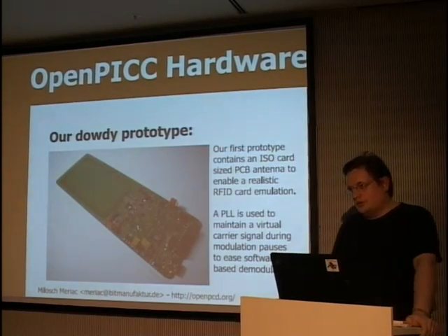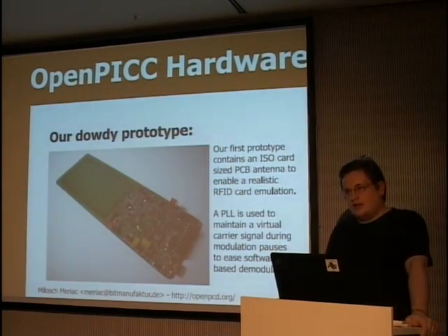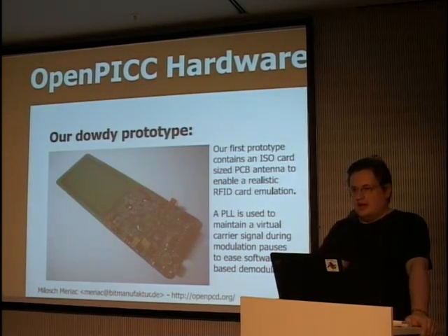And this proved also to be very helpful, because then you can instantly dump the data you got over DMA. You just, for example, assign an underscore to 0, say a high level, and you can instantly print it on a console, and you see the bit pattern like you would see on an oscilloscope.